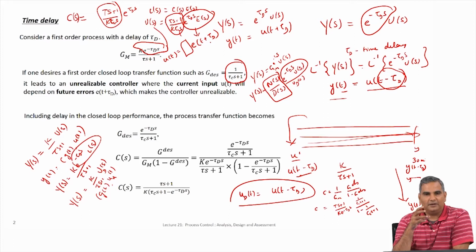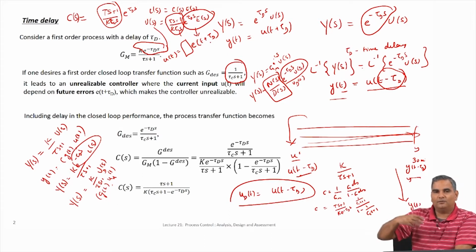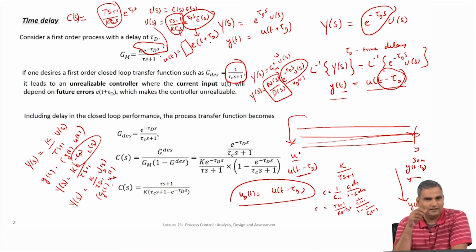So basically what it means is there is a transport delay. Though you have opened your hot water knob, this action is not going to immediately result in hot water coming, right. All the water in the pipe has to drain out before the hot water comes, so that introduces a delay. But typically, when you open the knobs for hot and cold, your mind says hot water has to come in, but hot water is not coming in. So the first thought that comes is really not time delay, it is that maybe I have not opened the knob enough, so the flow of hot water is much lower than the cold water, and that is why the water is still cold.